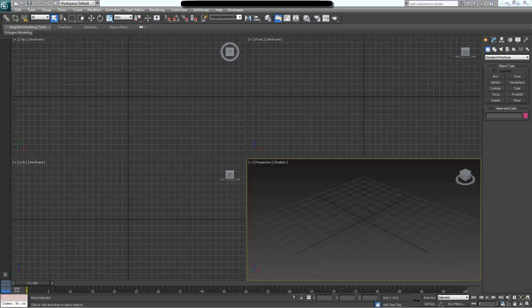A very useful thing to have when creating geometry objects or modifiers is the ability to raycast, and that is the ability to take a point and cast a ray from it into some kind of direction and see where it hits some object or some other mesh. And this is something I want to explore in this tutorial by creating a tool that will essentially take a mesh and project it onto another mesh without altering its topology.